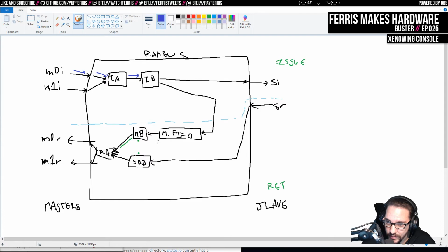Okay, let's say these both have data in them. Right, so how did they get that data? Let's walk through that. So again, we'll use this blue color. So first we issue this, and then we issue this. On the following cycle, because this was able to read and it was empty, this then reads. So following cycle, or during the same cycle actually, this issues that read because we have write through here. So on the following cycle, data comes in here and data comes in here.